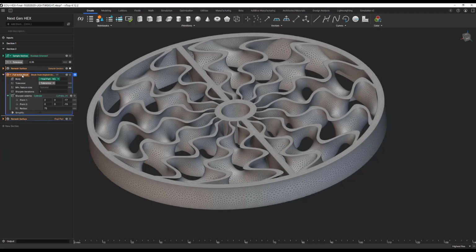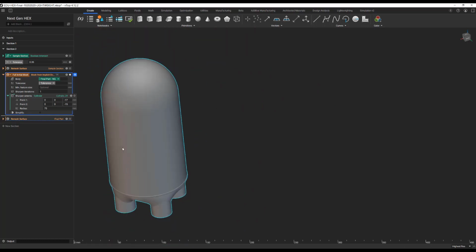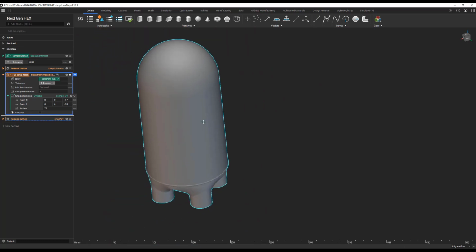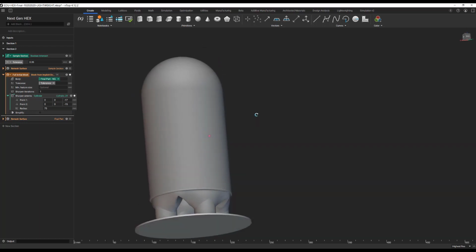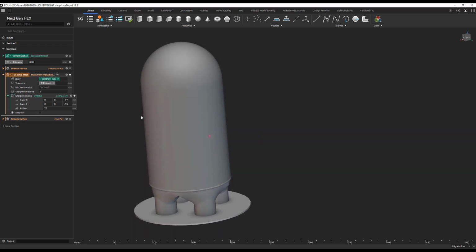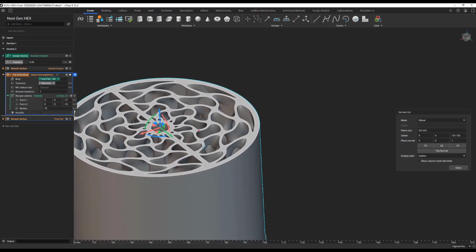Starting with the initial mesh, in this case, I am concerned with sharpening some of the edges, primarily down at the bottom where I want to define my boundary conditions. So in this case, I just have a thin cylinder intersecting those bottom feet. Same tolerance input and sharpen iteration set to 1.